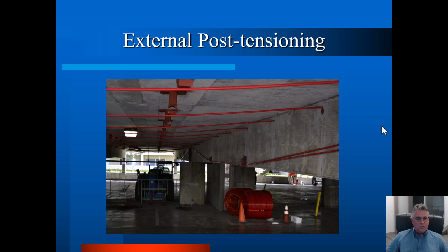Now, most other methods of fixing a building involve applying a lot of load in concrete. You're adding or shooting on another slab. You're adding a lot of beams. You're adding something that has weight to it. And then you have to consider that weight on the system, on the columns, on the foundations, on the seismic design. Post-tensioning is negligible weight and can be applied in a building and give it tremendous strength.